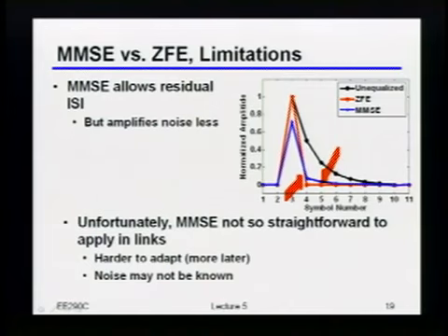Unfortunately, there's some not so good news about this. Despite MMSE being very interesting, if you talk to the comms people, or do any kind of wireless work, they'll say, oh yeah, I have an MMSE equalizer. It's very, very rarely used in links. There are two straightforward reasons. The first is that it's trickier to figure out how you actually adapt this equalizer, which we'll talk about more later on.